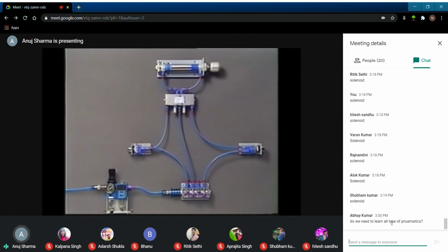In most applications, it's rare for cylinders to be directly actuated. Normally, control and signaling are accomplished using discrete components. In this circuit, two push-button directional control valves send signals to a 5-2 directional control valve. When a push button is pressed, the cylinder is actuated. Another benefit of indirect control is that even if one of the push buttons is pressed momentarily, the cylinder will complete its full operation. This is because the control element stores the signal.